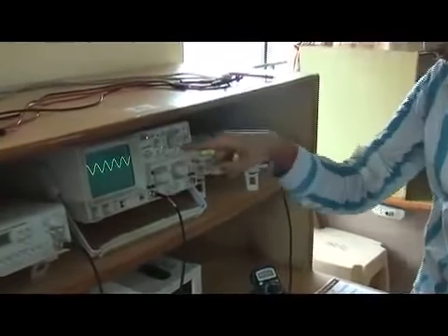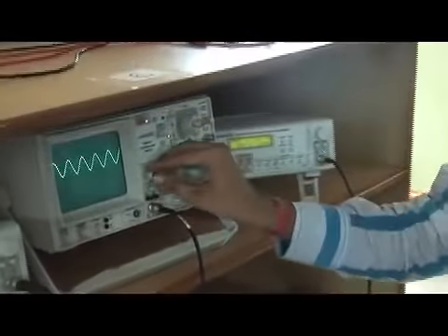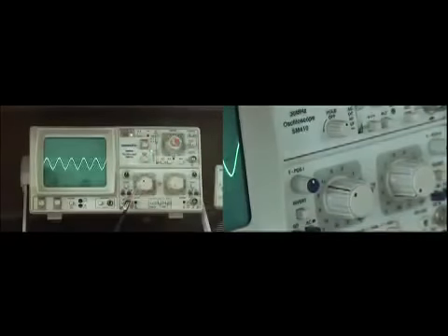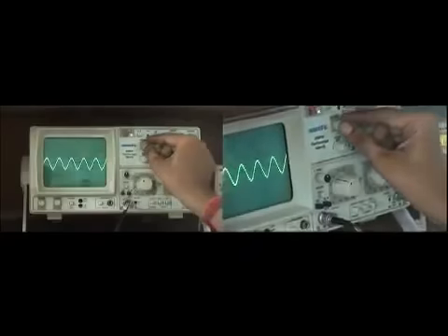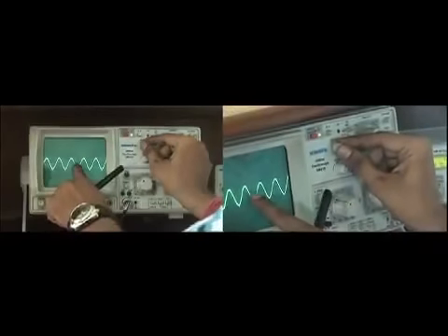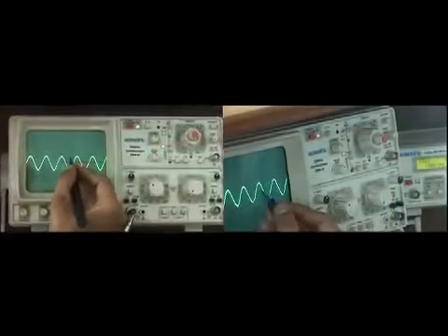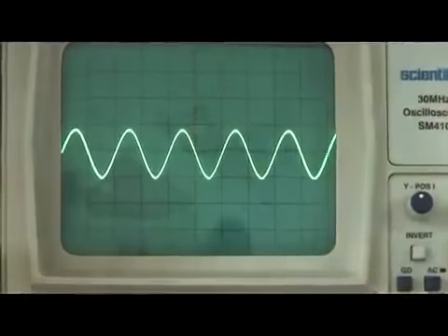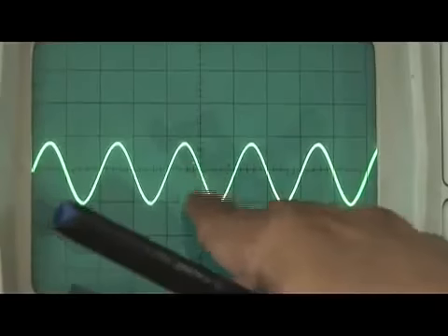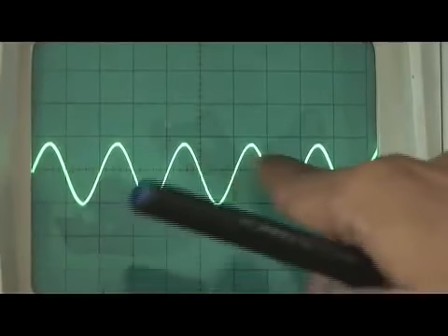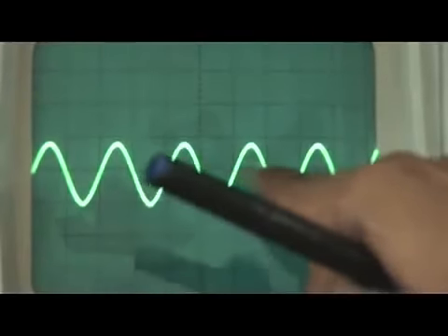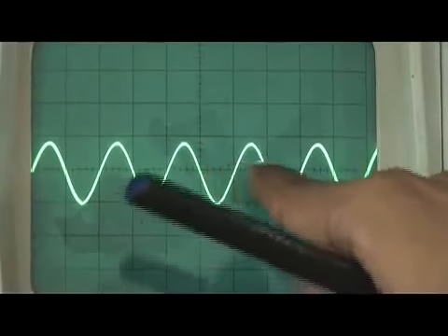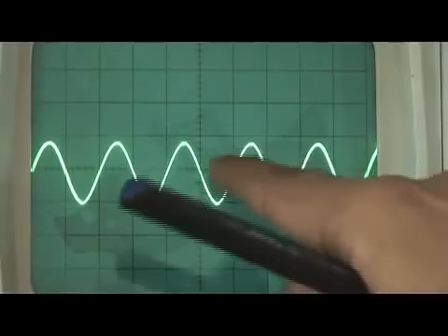Next we move to how to calculate the frequency. Again make it ground, bring it to the center of the line, release the ground, and set this y-axis in such a way that you can easily count your one cycle. If I set it here, from this point this is my one complete cycle till here. How many blocks does it require? It requires 1, almost 2, or let us take it as 2. So it is 1 block, 2 blocks. To complete one cycle it requires 2 blocks.